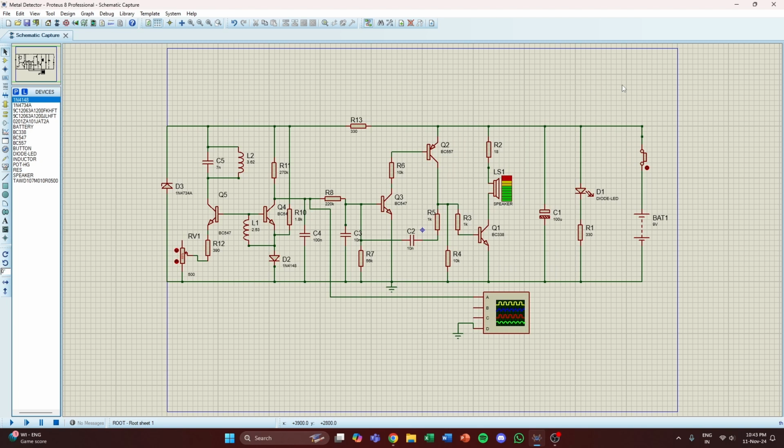The capacitor takes a very short time to charge and a longer time to discharge. This is why the output consists of very short spikes. Now we come to the reason why the frequency alters. As the voltage from the previous building blocks rises, the charge time for the first 10N capacitor is less, and thus the first transistor in the oscillator circuit is turned on in a shorter period of time.